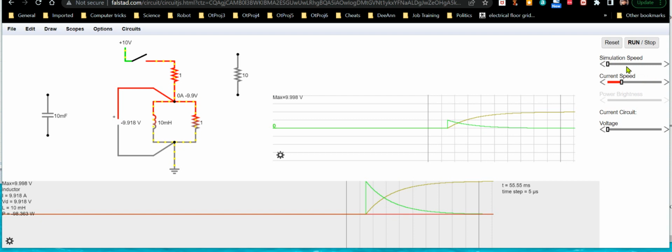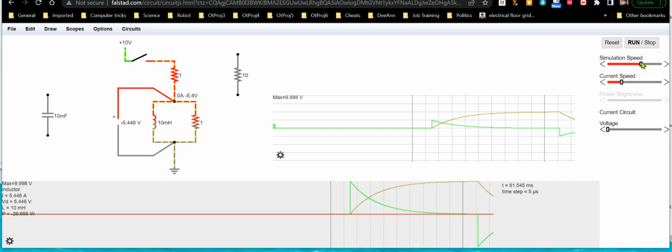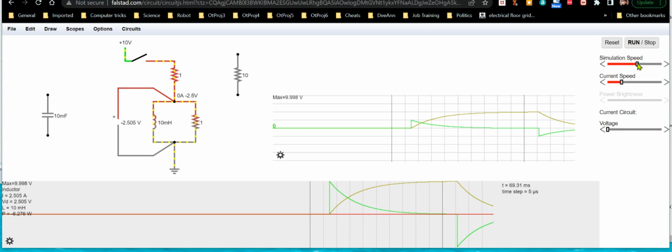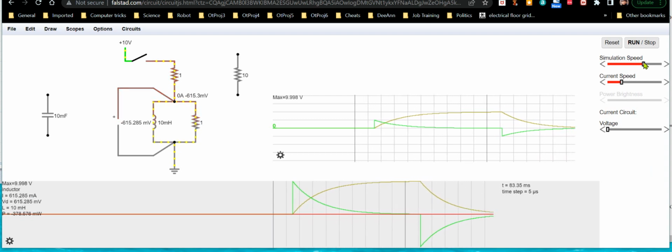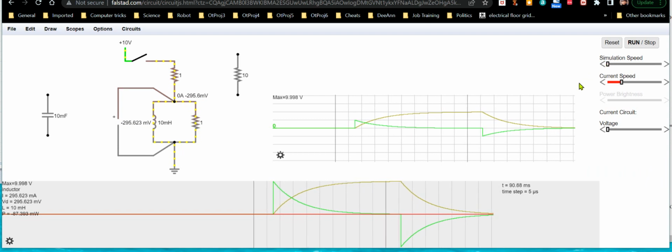The flow direction is still the same, because what the inductor is doing is, like I said, inductors don't like current to change going through them. So they'll put whatever voltage across themselves they need to try to maintain that current. Now let's see what the ramification of that is. Oh, look at that. The voltage has gone negative all of a sudden. That's interesting, and the current is falling off at that same period. So basically it generates a negative voltage so it can try to maintain the direction of current flow.